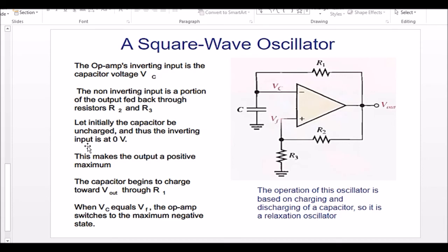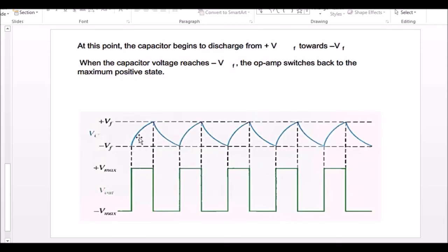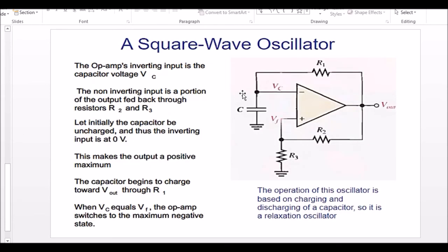So initially your capacitor voltage would be a rising curve, up to the point it is charged to the maximum value of Vf. Whatever voltage is appearing here is charging up your capacitor. Up to that specific point when it's completely charged, your comparator will flip your output voltage, because the maximum voltage here exceeds your comparator reference, so your output would be flipped.